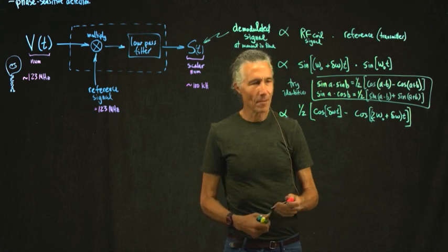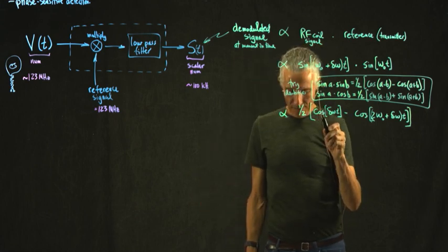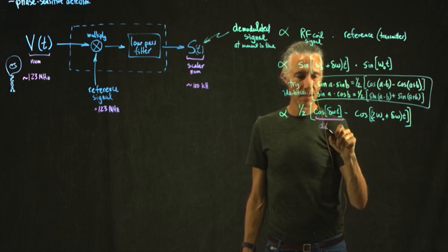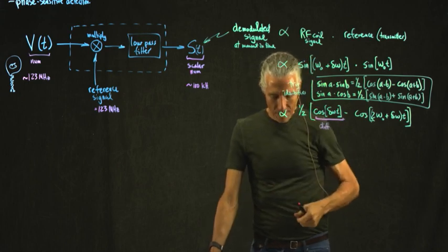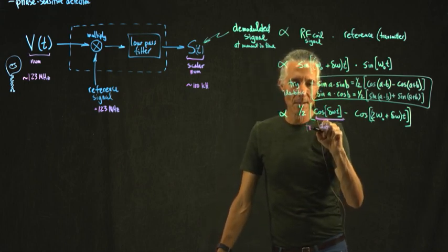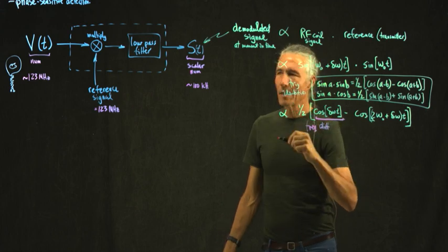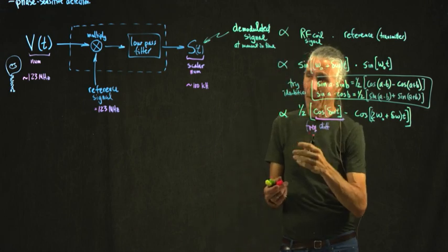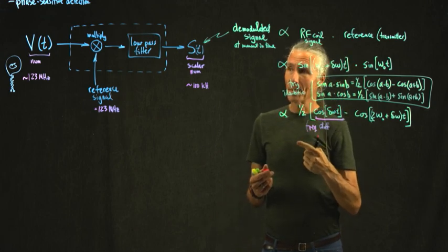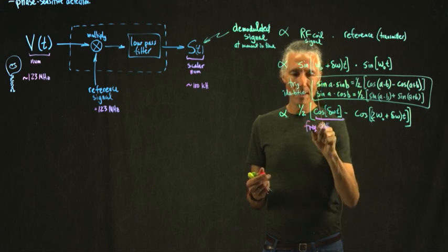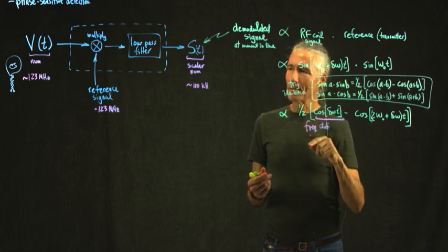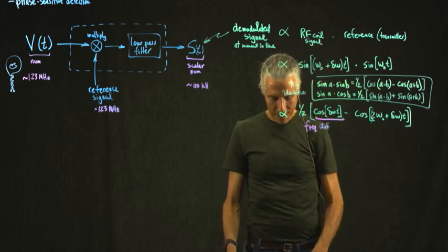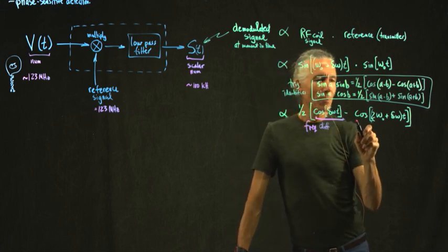Basically, this is going to be what we want. This is the difference. It's the frequency difference between the signal coming out of the brain and our transmitter frequency. Could be 0 if it happens to be exactly the same as the transmitter frequency. But typically it's going to be oscillating back and forth between different frequencies, different frequency offsets. And then this one we filter out.